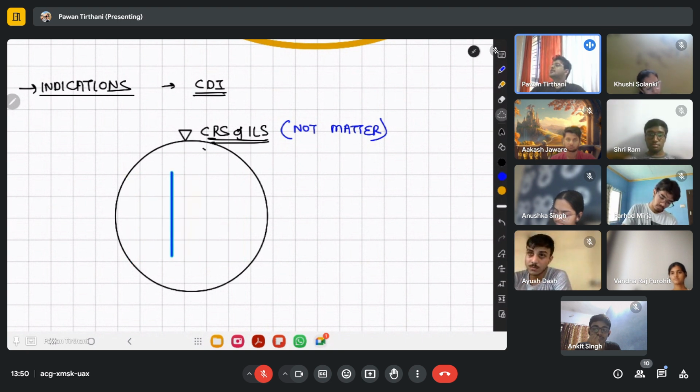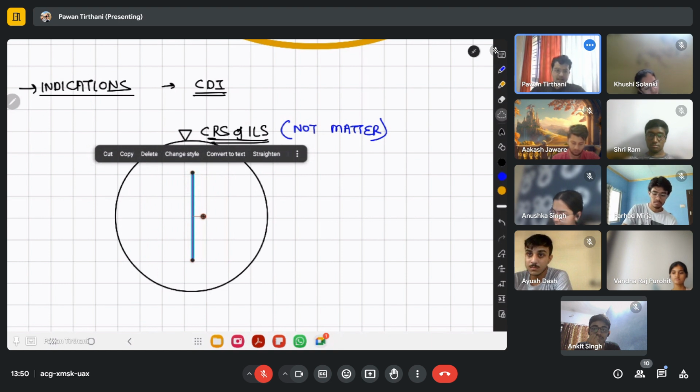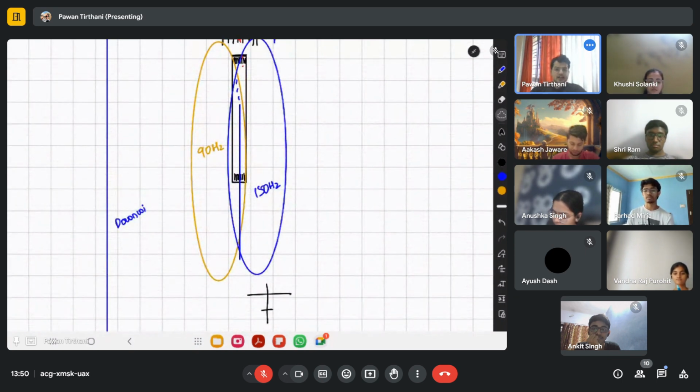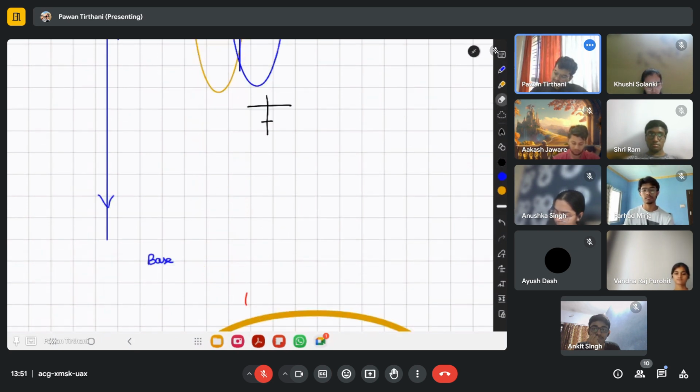Am I getting guided? I don't have anything to look at outside. It's completely cloudy, pitch dark. But yet I am guided by this small little needle and I can fly the aircraft very well with this. And the indications are a little bit more precise than the VOR signals. This localizer is more precise than a VOR because